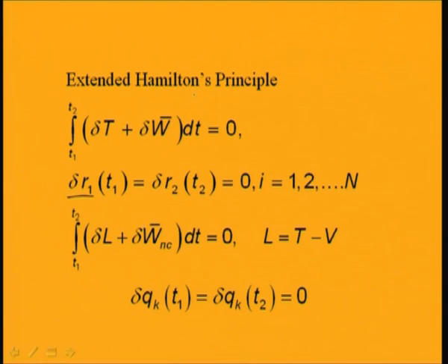So, according to the extended Hamilton principle, when the virtual displacements equal 0 at times t1 and t2, the system will obey this principle, that is, integral of del T plus del W bar dt equal to 0. Here W bar is used because work is a path function.